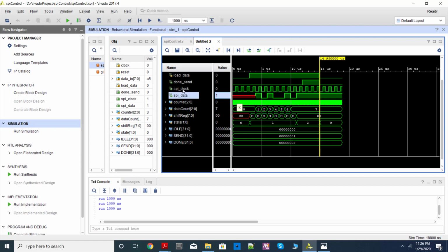So basically, your external SPI clock should be running starting from here all the way to 1 2 3 4 5 6 7 8. Okay, it should run only till here. On this edge onwards, it should be flat, it should remain high. Same way, before this edge, it should remain flat. So that's what we need to do.